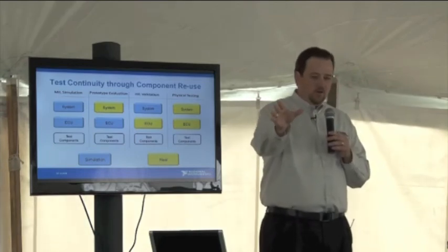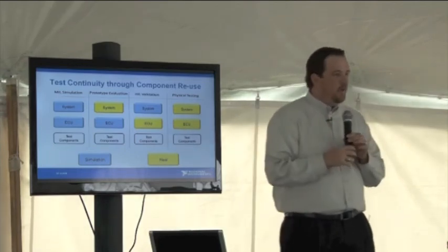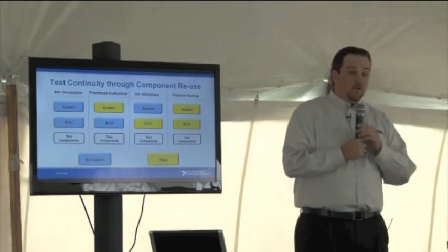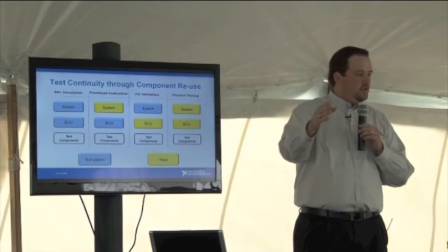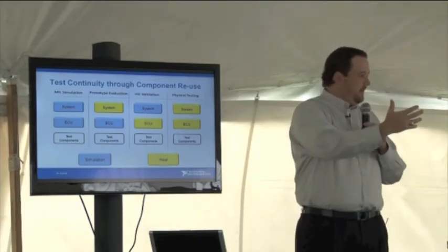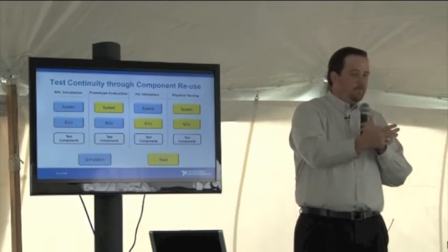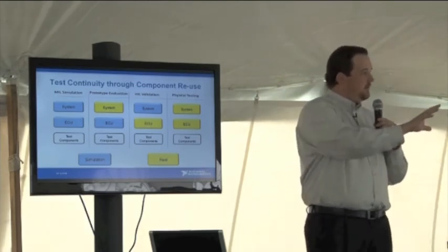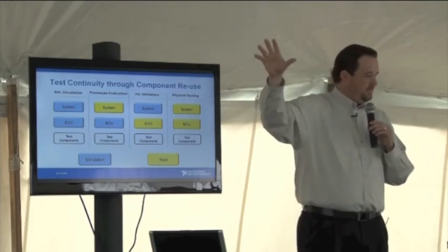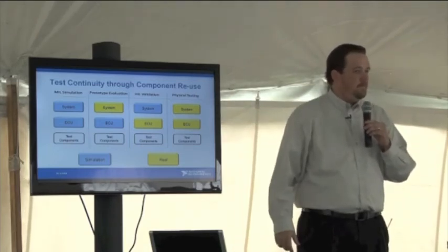So the test cell engineer looks at the results that we're seeing on the dynamometer and compares them to what was done in simulation. And they can identify: did we have an error in translation as we moved from a model to actually deployed code? Or was my plant model not accurate? And do I need to refine my plant model so that the next time my design engineers begin a project, they have a more accurate representation of what it's going to be like when it gets down the road to me in the real world?